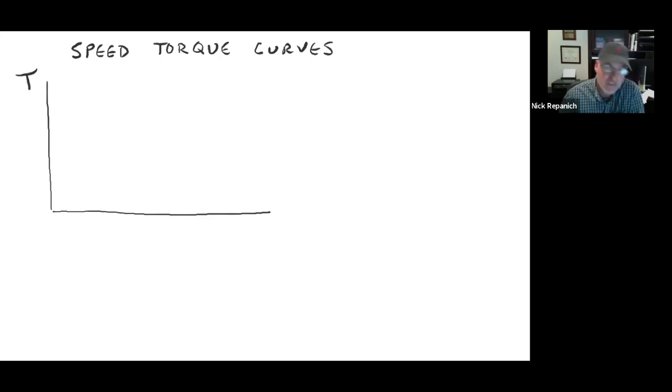A typical stepper curve has sort of a constant velocity or constant torque at first. And then the nature of this motor is it's a positioning motor. It's designed so that it can do positioning without you having to do any external feedback to keep track of the position, meaning it does what you tell it to unless it's completely inoperable or stalled.